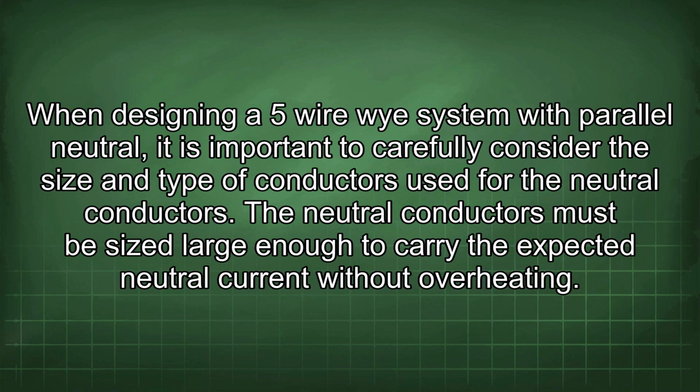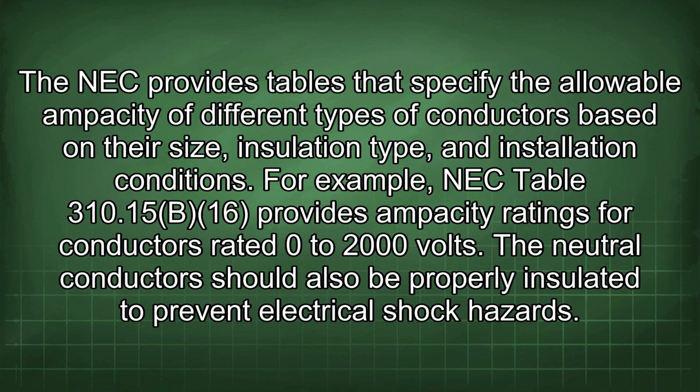When designing a 5-wire Y system with parallel neutral, it is important to carefully consider the size and type of conductors used for the neutral conductors. The neutral conductors must be sized large enough to carry the expected neutral current without overheating. The NEC provides tables that specify the allowable ampacity of different types of conductors based on their size, insulation type, and installation conditions. For example, NEC Table